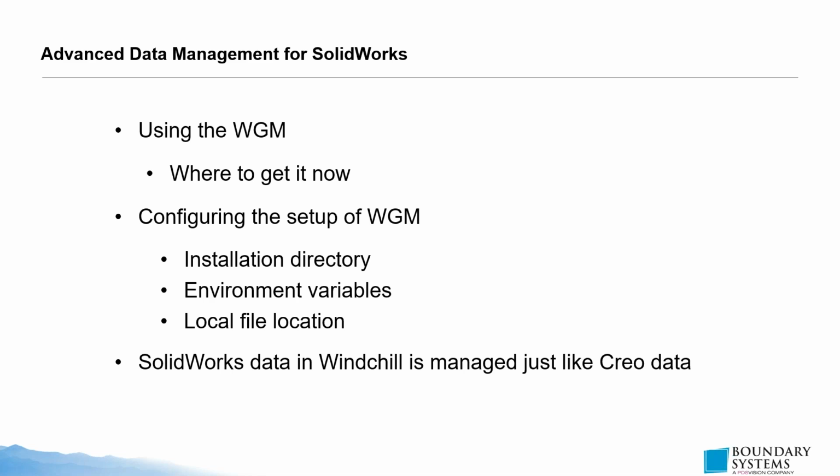So you can download the latest build, and it still works. The benefit is that your Windchill system can stay at the same build code, but I can have the latest build code for my Workgroup Manager, which now works with the latest version of SolidWorks.